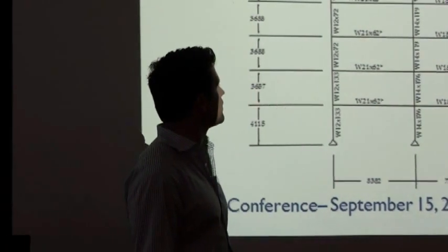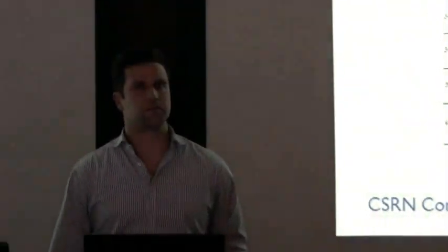Okay. So when you add this, say the Scorpio, this will bring a lot of axial force in the column. How do you consider this as part of the model? What I did is painstakingly I checked every column, the axial load and the moment, and I did a verification in Excel to see the interaction ratio. So I checked for column buckling, which is I'm assuming what you're getting at.